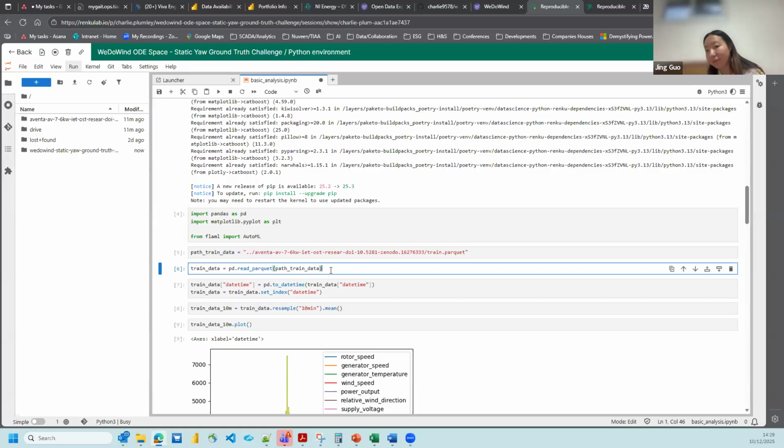Right. Yeah. There are some nuances to that. Sometimes 0 is not actually where you maximize production. Sometimes there is a slight offset because of the physics of the rotor and the flow behind it hitting the wind vane or wind sensor, so you actually want to apply a slight offset to maximize generation. So you do see on some turbine models that there's always an offset.